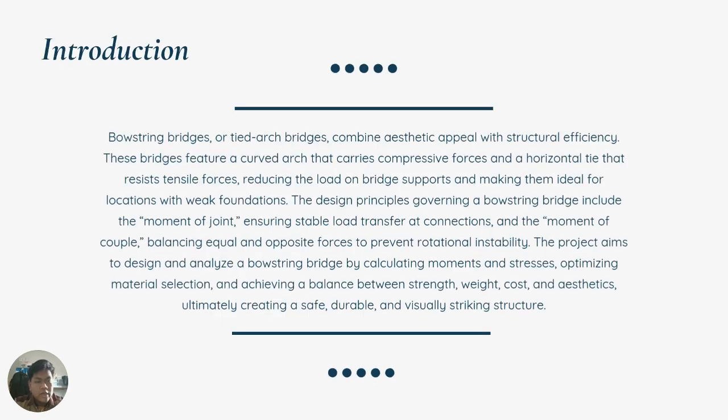Bowstring Bridge or Tied Arch Bridge combine aesthetic appeal with structural efficiency. This bridge features a curved arch that carries compressive force and a horizontal tie that resists tensile force, reducing the load on bridge supports and making them ideal for locations with weak foundation.